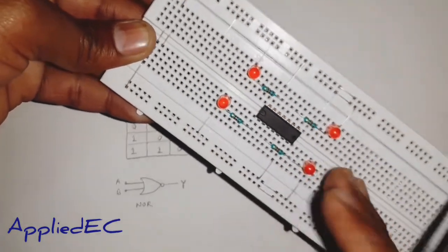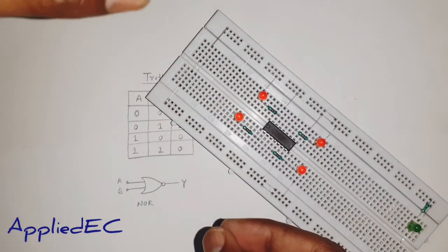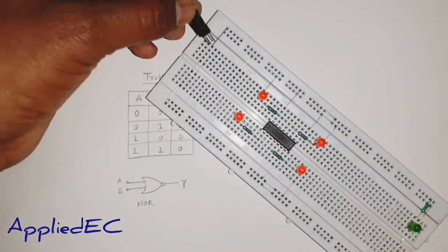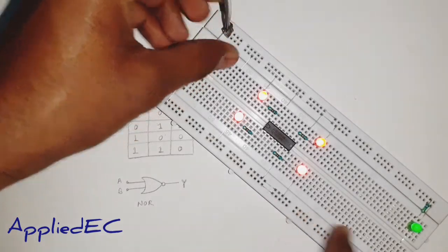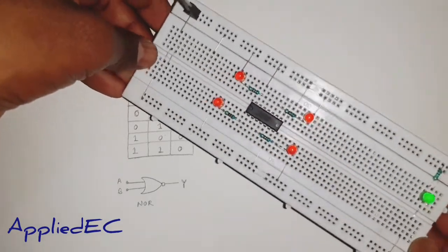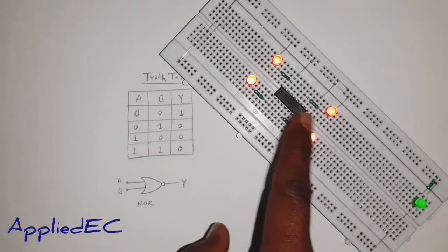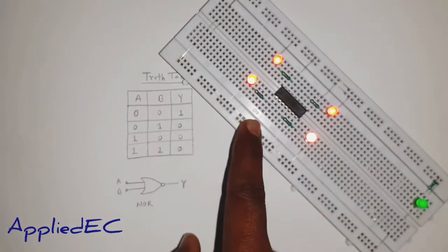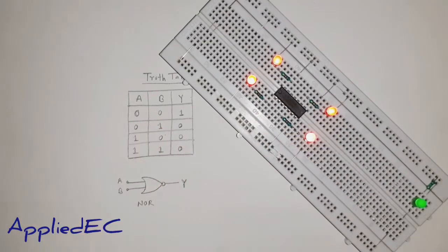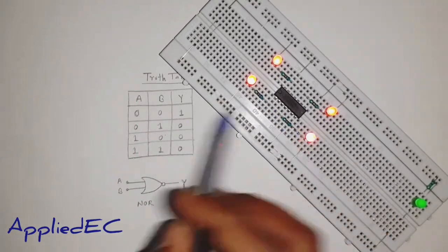So let's connect the IC to the power. So this is a 5 volt power supply I have made with a typical phone charger. So let's connect. So as you can see, this one is to show the power in the IC, and all four gates are now 1 because we haven't applied any input on any gate. So this explains the first situation, 0 and 0, then all outputs are 1.